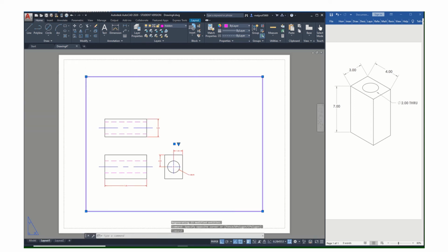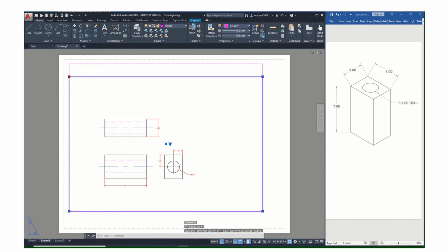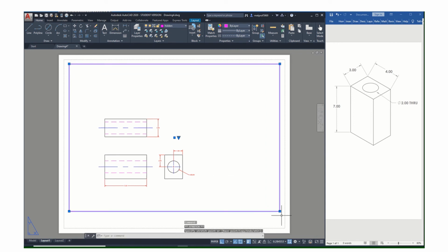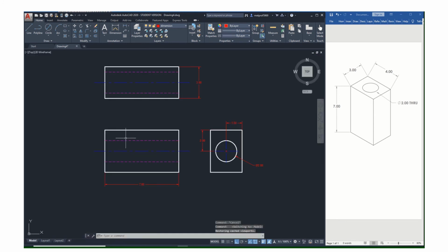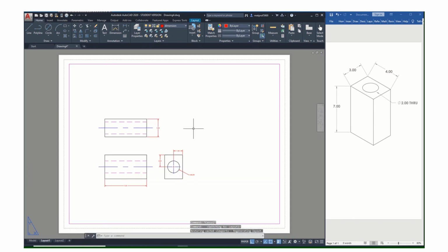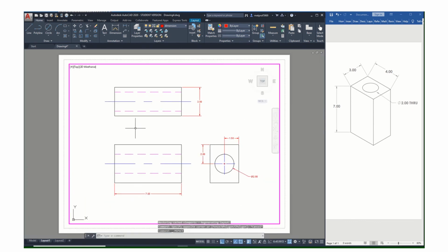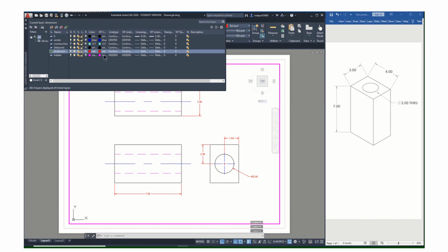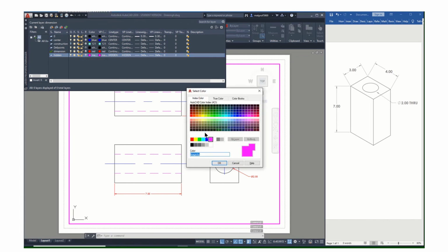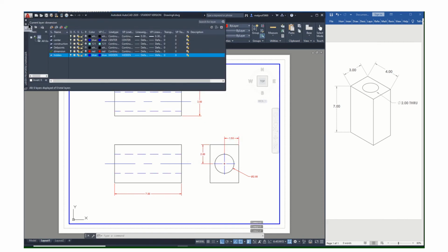And then as we've always done now, notice the color of that border. What layer is that? It's one of my, oh, it's the hidden line layer. Now that could be a problem, like I don't care about the border so much, but this is a really light color. It's not going to print well. When you get to this point and you think you're going to print it out, you can come up here, oops, sorry, go to your layer control, and you can just change the color, right? Just make it something darker. And then you know it's going to print.